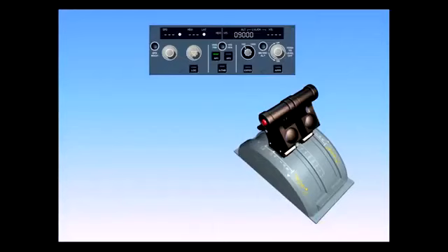If the autothrottle system has been switched off during flight, re-engagement is accomplished by pressing the autothrottle push button on the flight control unit. To avoid sudden abrupt power surges, it is recommended that the thrust levers be left in their present position until the autothrottle system is re-engaged. Then the thrust levers should be smoothly returned to the climb detent.